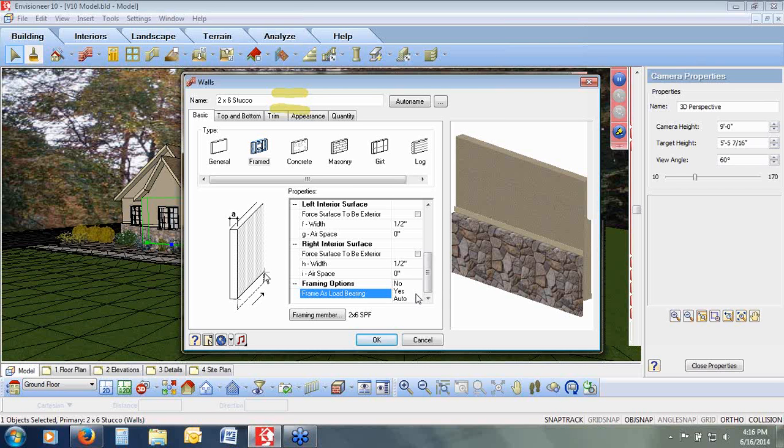And then in the catalog itself, have a wall designated, an interior wall, as yes, so that upon insertion it knows that it is a load-bearing interior wall, and it will get the header sizes automatically correct for you when it's going to frame the wall. That is a huge improvement for version 10, the ability to automatically recognize load-bearing versus non-load-bearing for all of the header sizes that you're going to be putting into the software.